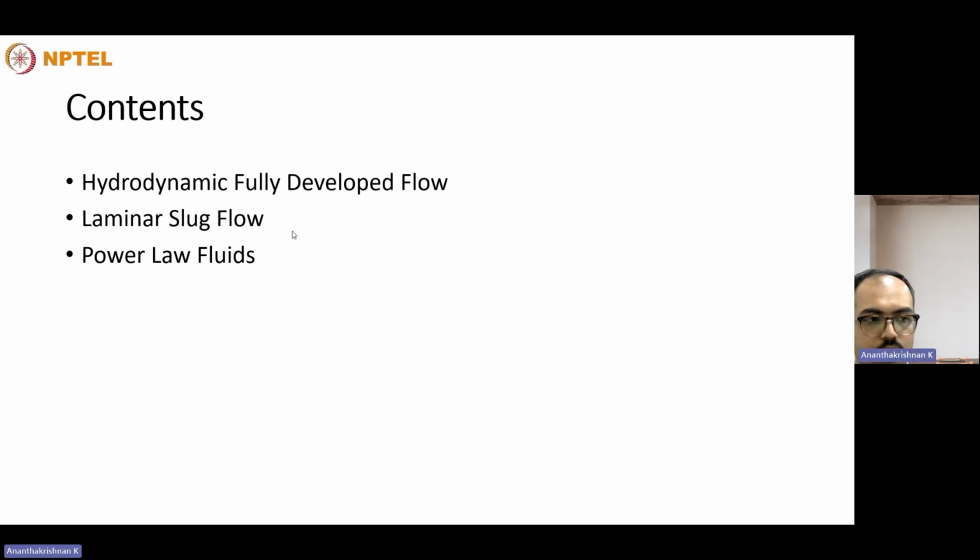That is what he has discussed on power law fluids in this week's lectures. In today's tutorial session, we'll see a few numerical type questions. I beg your pardon, it was 5.78 for the slug flow, n equal to infinity case at a constant wall temperature. So the variation would be from 3.66 to 5.78 for a uniform wall temperature when it moves from Newtonian to slug flow.